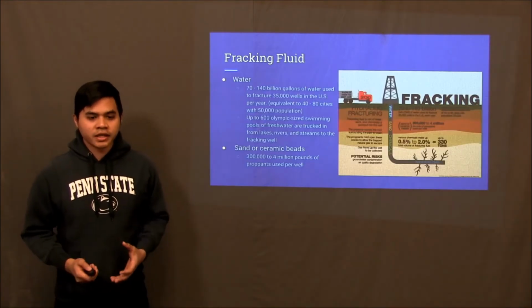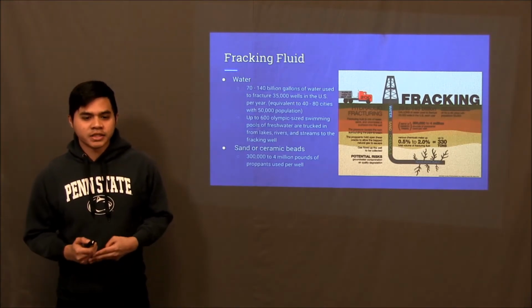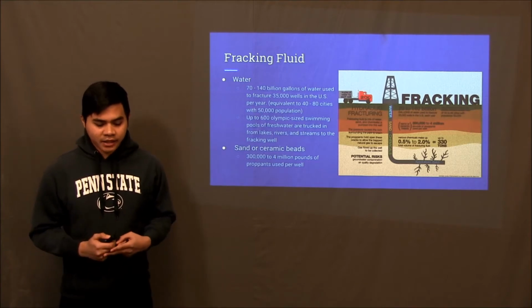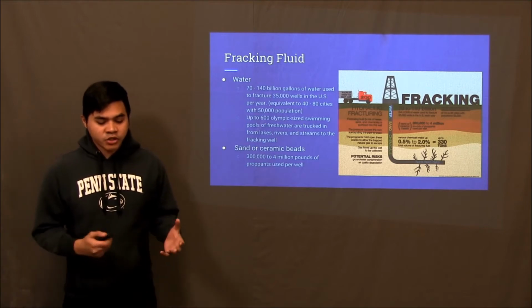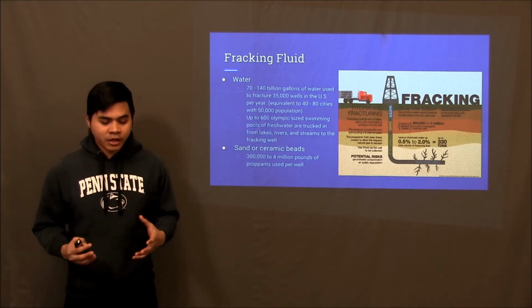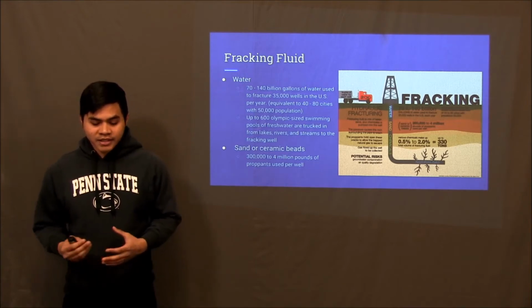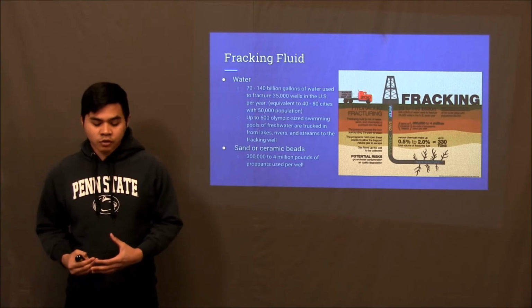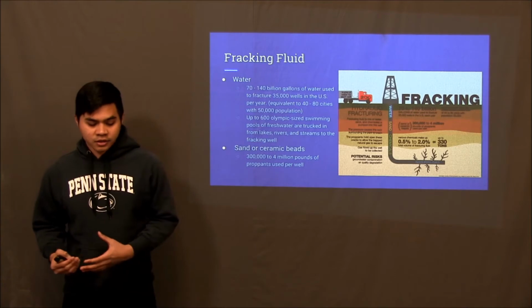But what goes in a fracking fluid? So there are 3 major components that go into a fracking liquid. First off, water. Second, sand. And third, chemicals. The mixture of water, sand, and chemicals is pumped at high pressure underground and wedges rock apart. The sand stays put in the cracks, creating pathways for oil and gas to travel towards the well. And about 40% of the water and chemicals flow back to the surface.